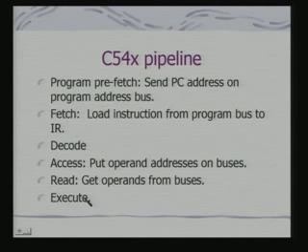You can understand the basic difference with, say, the ARM pipeline. In the ARM pipeline, the operands were typically part of the registers. So, there was no pipeline stage for getting the operands from memory. In this case, you are getting a sequence of data values, maybe in a block processing mode, which is stored in different data memories. So, you put operand addresses on the bus and then get operands. So, these two stages come into the pipeline.